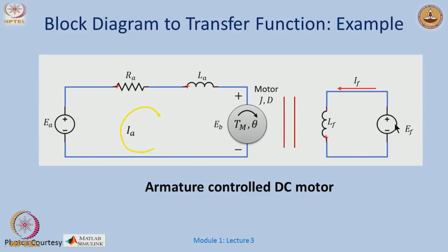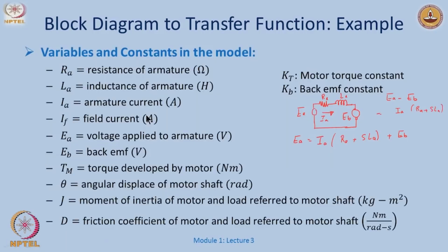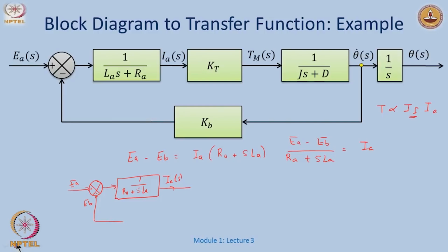Therefore, what is variable here is just the armature current. As the load varies, the armature current would vary, and therefore, I can rewrite the torque as T is some torque constant times the armature current. Okay. So, I will have K T and the T m here.